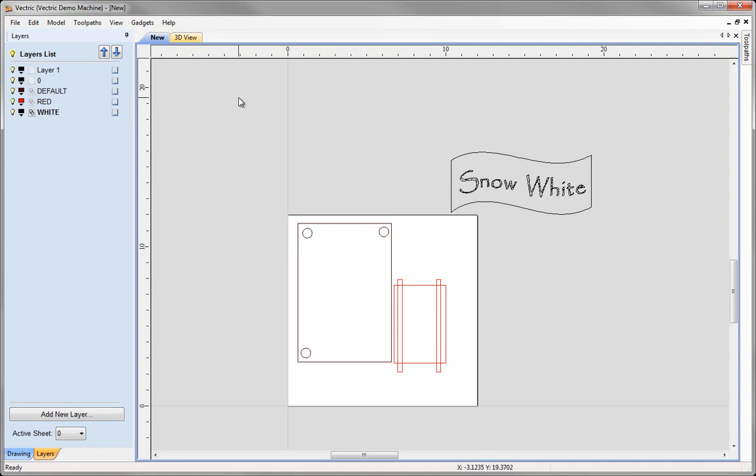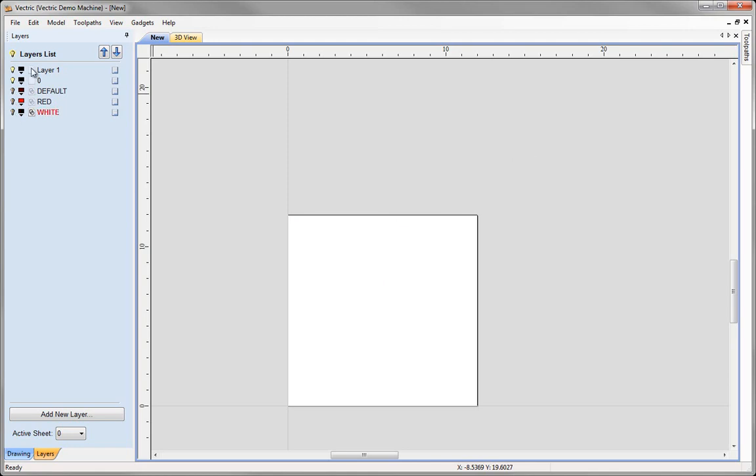Now the way to delete a lot of layers is to use the visibility first to effectively highlight which ones you're interested in. So I'm going to turn off the visibility of the ones we're going to keep so that only the layers that we're about to delete are left highlighted. Obviously they've got no content, so I can't see anything in the 2D view, but crucially I can now right click anywhere on here and have merge visible.